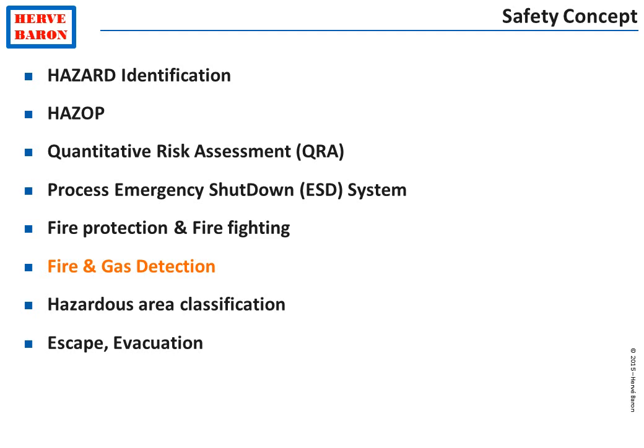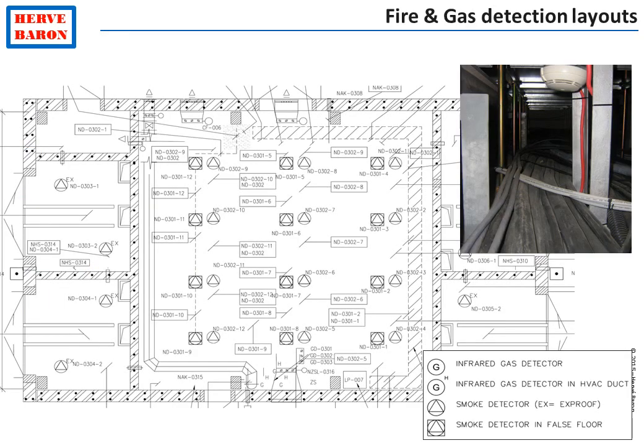Safety designs the fire and gas detection system. The fire and gas detection system gives alarm and executes automatic actions such as process shutdown, shutdown of building ventilation, release of firefighting agent upon fire or gas detection.